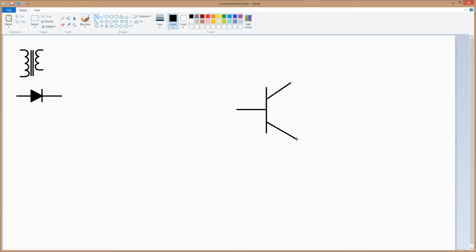And now we're going to put the little triangle on it. Well, first let's even them out. So see if I go to the selection. Here I'm going up with the wire coming from the collector. And then we want to have the wire on the emitter at the same point, so I'm going to use a selector tool. Start up here to size it, go straight down and cut. That makes both of these wires the same size, and go get a wire and run down on it.